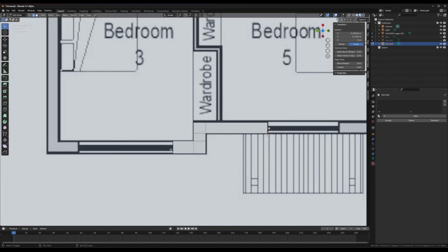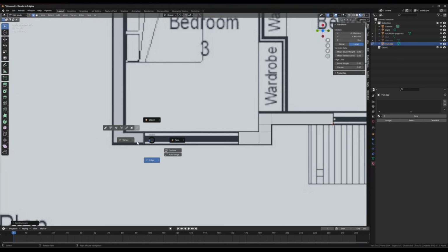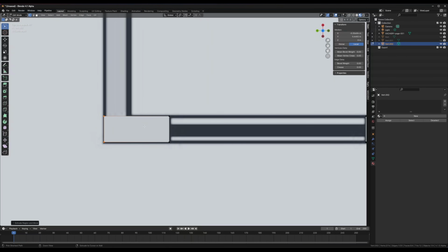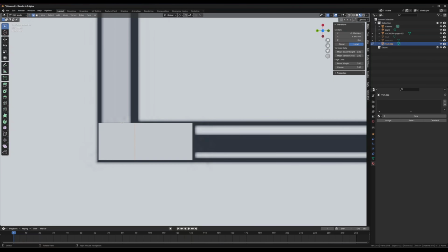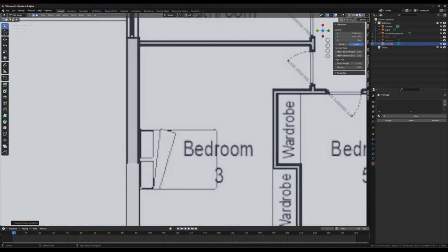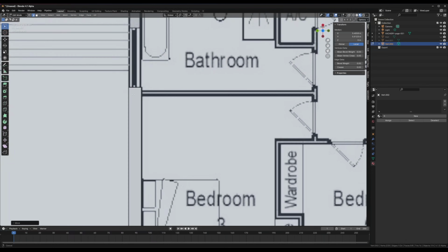So we might just get this edge, Shift D, duplicate the edge over, come into vertex mode again, extrude them over. And then we can just press Control R, loop cut, slide it in the middle, select the edge in edge mode, extrude it up. And we can just keep going. We can press G to just drag this up because we don't want more verts if possible.